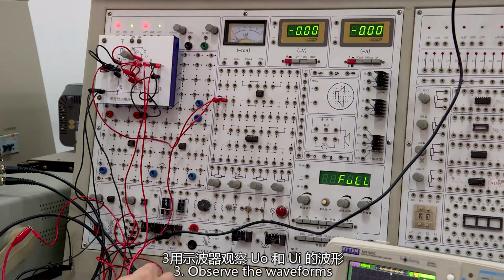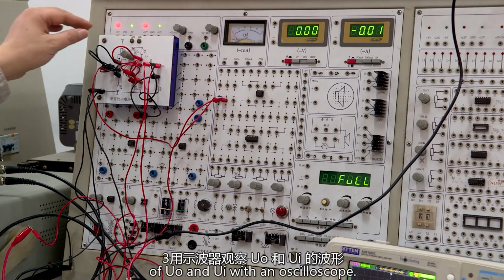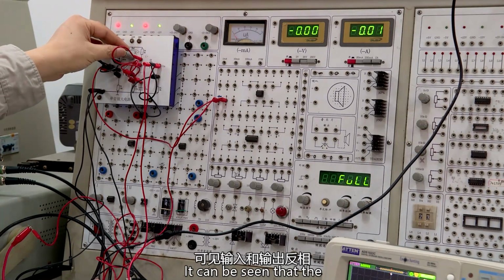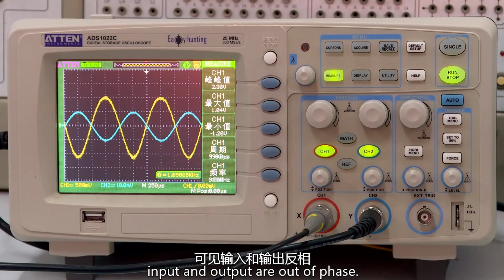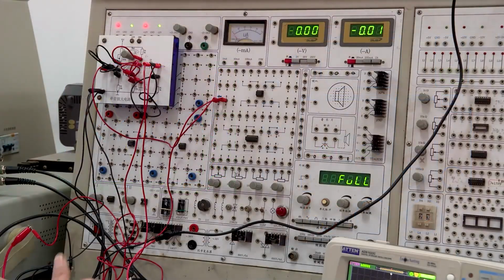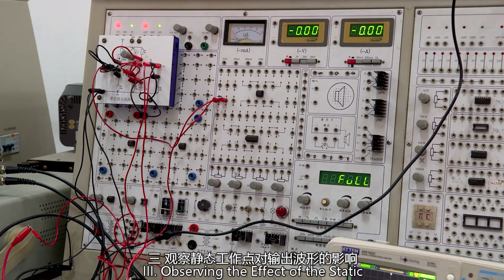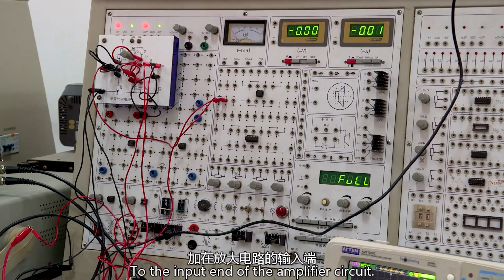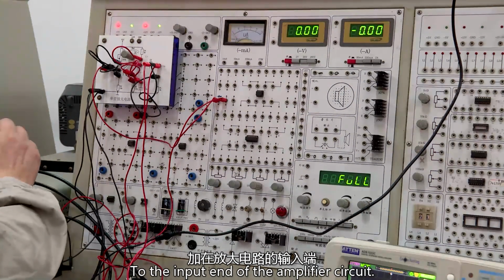3. Observe the waveforms of Ui and Uo with an oscilloscope. Compare their phase relationships. It can be seen that the input and output are out of phase. Observing the effect of the static working point on the output waveform. Apply a sine wave signal with a frequency of 1 kHz to the input end of the amplifier circuit.